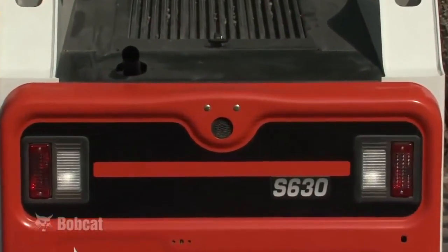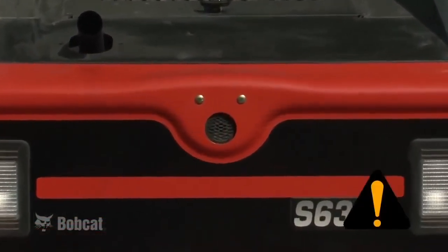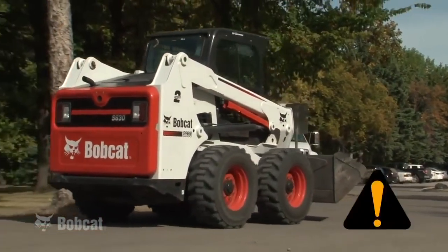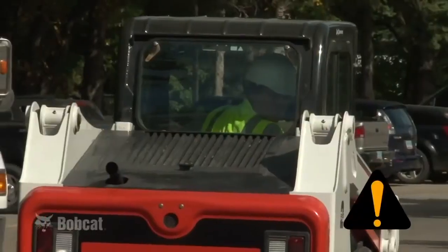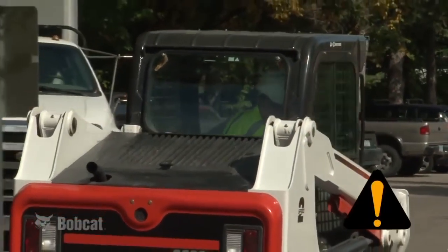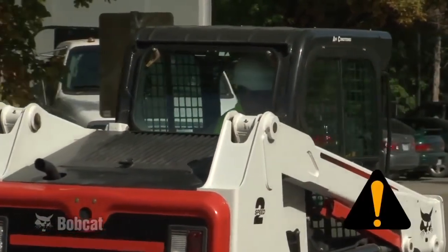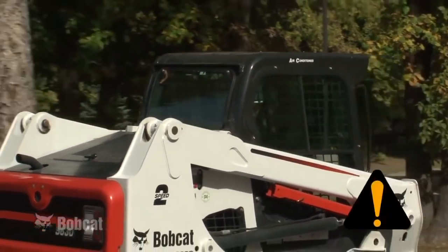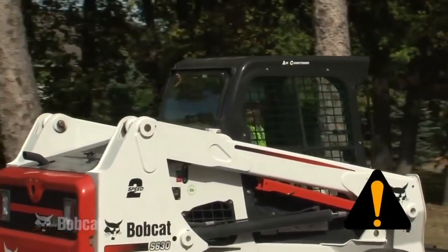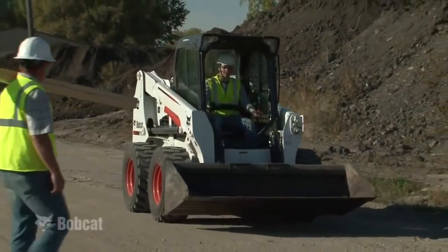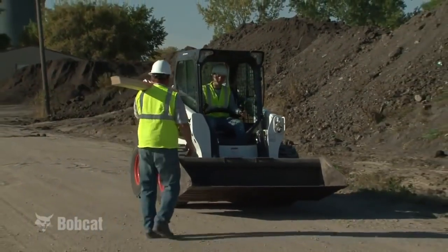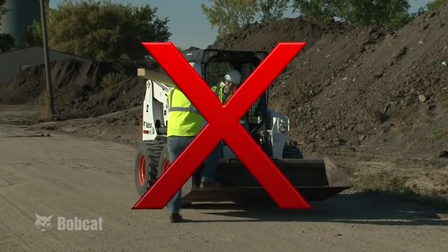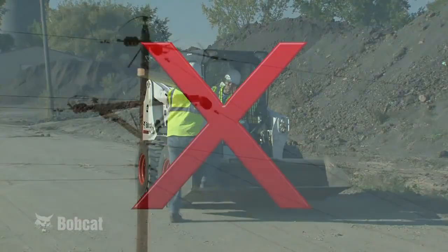If your machine is equipped with a backup alarm, it must sound when operating in reverse. A backup alarm is not a substitute for looking to the rear when operating the loader in reverse or for keeping bystanders away from the work area. The operator is responsible for safe operation. Never carry riders on the loader or on attachments. A Bobcat skid steer loader is strictly a one-person machine.